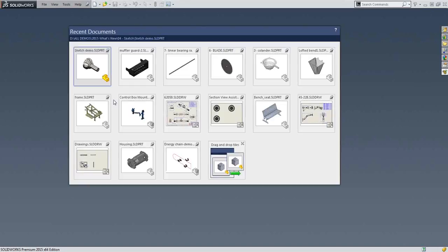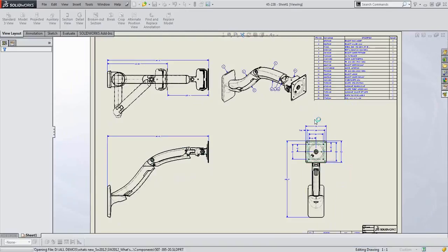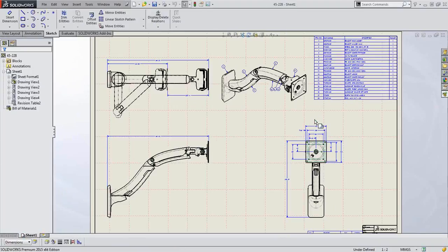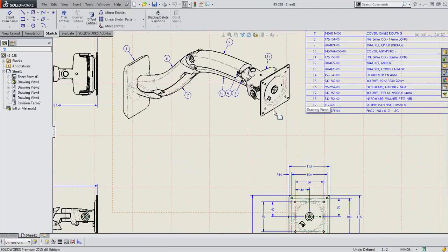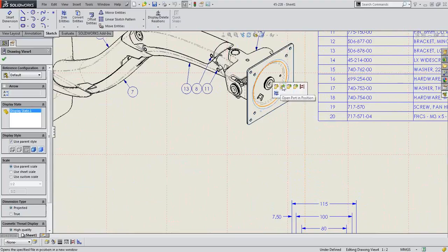Now one more enhancement that I wanted to touch upon is the change of dimensions and the way you can provide ballooning as well. You can make a sequential ballooning. So what I'm showcasing to you are all the enhancements which have been made over the previous 2 or 3 releases. So you see this particular part over here. If I right click on this, I have an option which says whether I want to open the particular part, or I have the option of opening the subassembly as well. So let's say I open the subassembly,